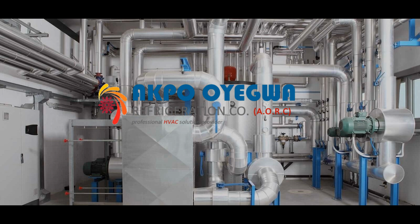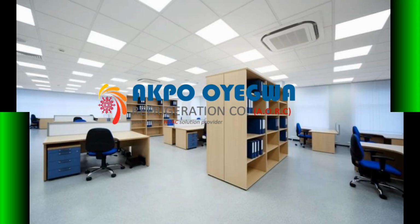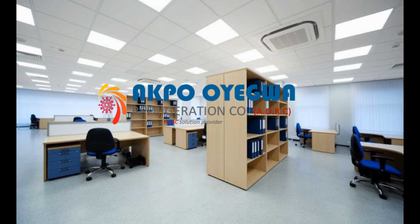5. Split systems. These systems have an outdoor unit and indoor unit which are connected by refrigerant lines. 6. Packaged systems. These are all-in-one systems that combine heating and cooling functions into one unit, typically located on the roof or outside of a building. 7. Variable refrigerant flow, VRF, systems. These systems use a variable speed compressor to adjust the amount of refrigerant flowing to multiple indoor units. 8. Hybrid systems. These systems combine two or more types of HVAC systems, such as a boiler and heat pump.